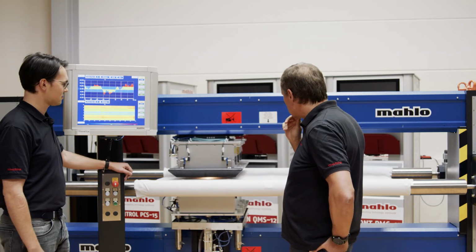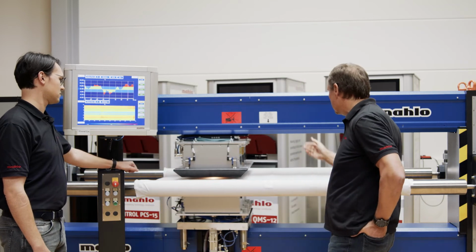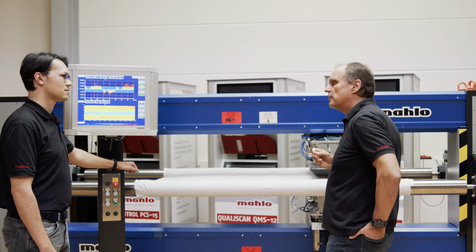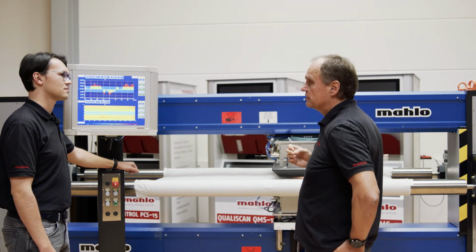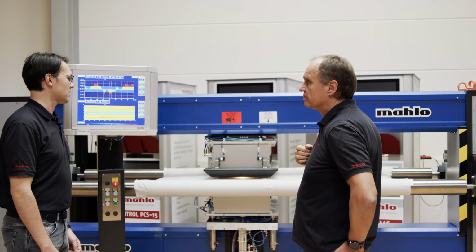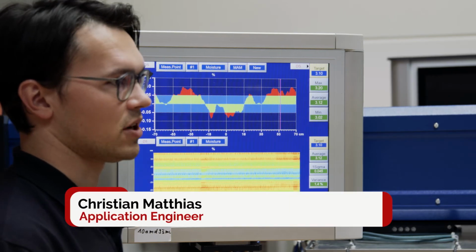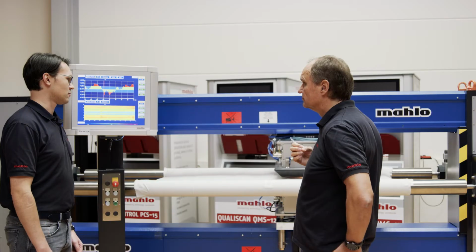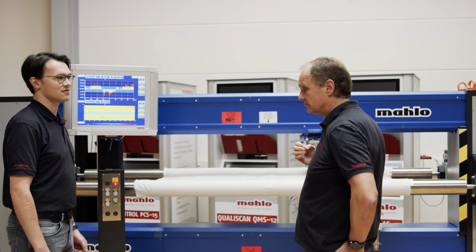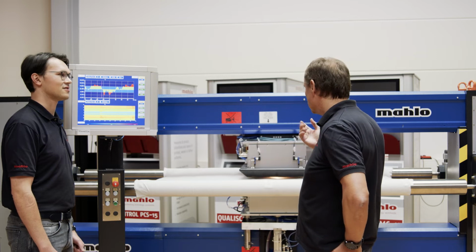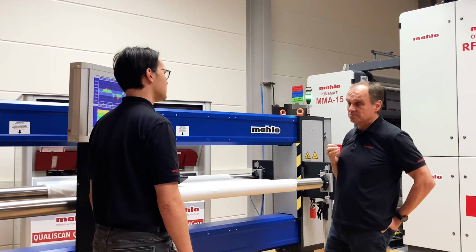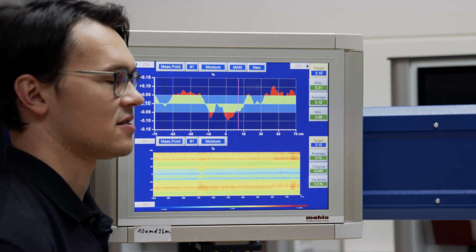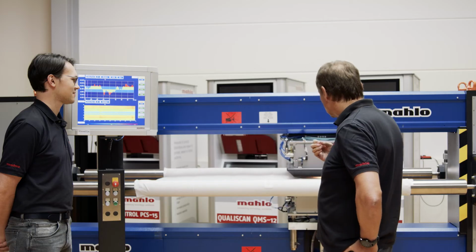Okay, what can we say about different colors? Now it's a plain white nonwoven, but it also could come along with a light green or blue or brown shade. Would this influence our calibration, and do we have to adjust something in that case? No, in this case, the color of the web or the color of the product doesn't affect the measurement at all. Of course, light colors are very good because they are similar to each other. So the answer to this question is no. The colors don't affect the measurement in this case for light colors. So this will keep the effort for calibration very low. Of course, and you can use the same calibration for the same product, even though the color is a different one. Yeah, so this is nice and impressive to see.